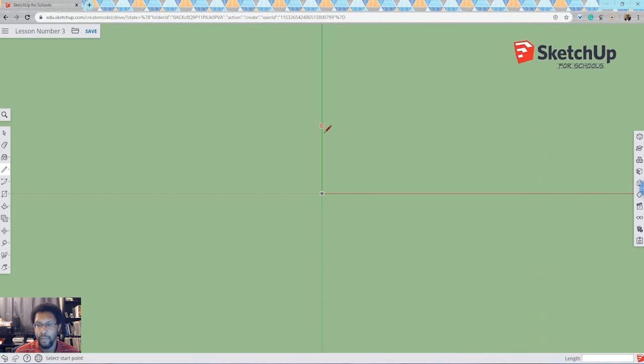and then we can start off by moving that cursor icon to the green line right here, and you can see once I move it close to it, it snaps into place and locks onto that green line, and then I can easily move it back and forth. That allows us to start off by making that first point that we're going to make connect to that line. Now the key thing when starting off with 3D modeling is making sure that all our lines are straight or parallel to each other. And I'll just make sure that, if we are printing something, we'll get a nice cube or rectangular prism shape.